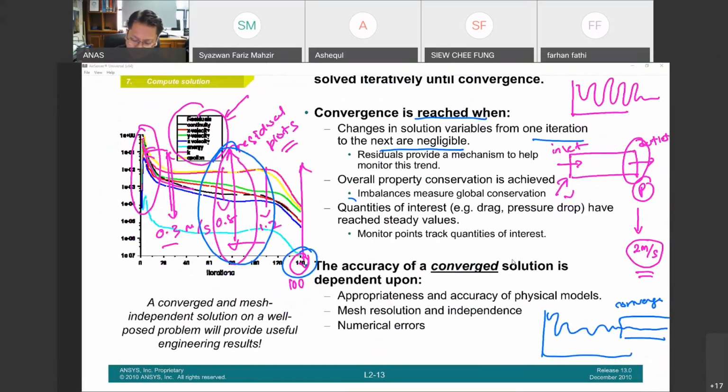So that's why you need to choose. In Ansys, you can choose which residual plots you want to look at. The plot is not there just as a show. It has a purpose, so it's important to understand all the purposes in Ansys. The quantity of interest which can be selected, pressure, velocity, XYZ axis, can be checked whether they have reached the steady state value.